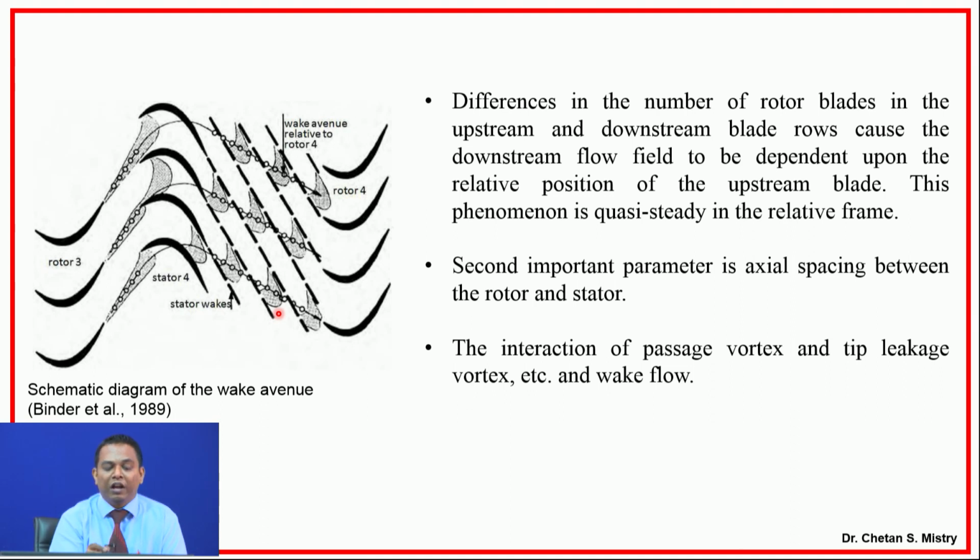So, under this condition, this is at some section, say the mid section. We have all kinds of three-dimensional flow. Near the tip region, we have tip clearance flow, which merges here. Near the hub, I will have horseshoe vortices, which create my three-dimensional flow. All together, that gives a very complex flow field.